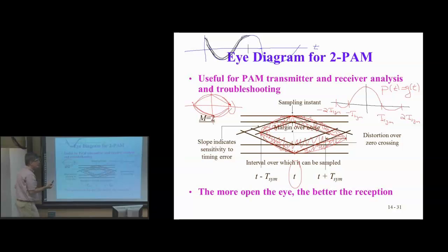Okay. So this eye diagram is an empirical way to debug and diagnose problems. You can see the noise, and at least you can get an empirical idea how good is the signal quality at that particular point. You can measure the transmitter output, receiver input, after the match filter. It can be almost anywhere in your system as a debugging tool.